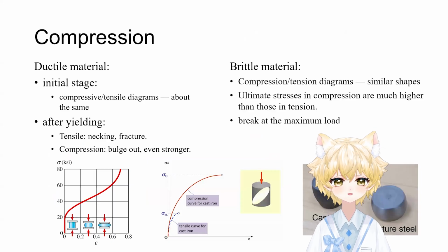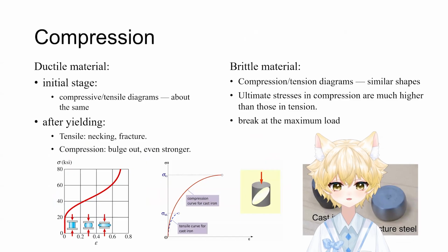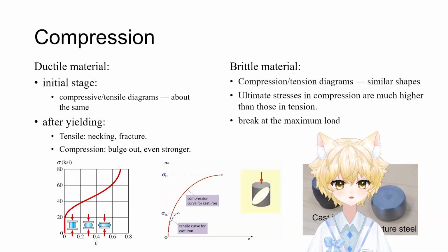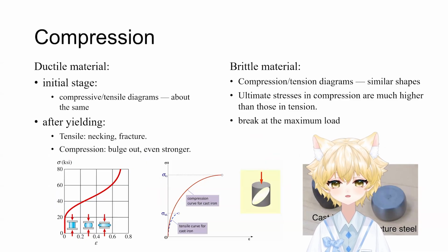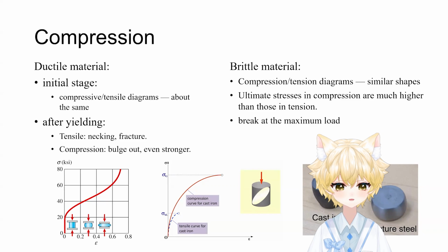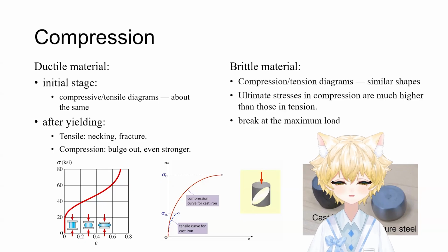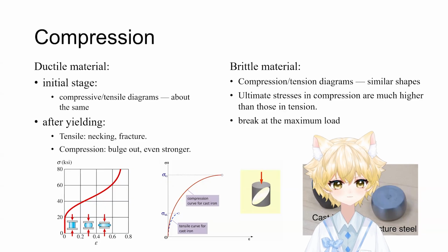Now, you may be thinking, if these brittle materials just snap without any warning, why on earth do we still use them? It sounds like a terrible idea to build a bridge or a building out of something that fails suddenly, right? But here is the redeeming quality of brittle materials. They are sufficiently strong in compression, at least compared to their price, right? Because they are relatively inexpensive. Let's look at their compression behavior.